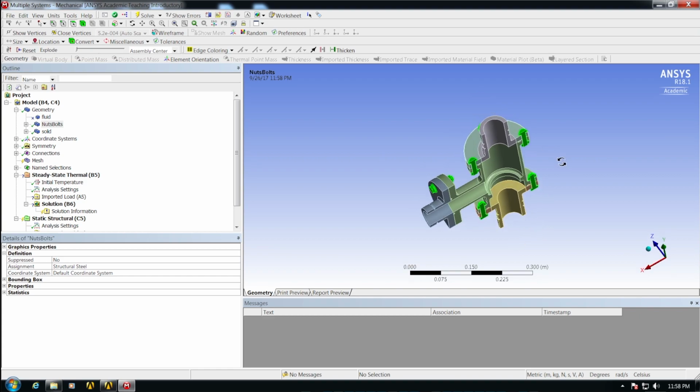One important thing to mention is you'll notice that this is cut along the XY plane down the middle. The reason is that this is a symmetric simulation. If you were to imagine fluid flowing through this pipe, the mean quantities of the fluid flow, the heat transfer, everything are symmetric about this plane. So they should be a mirror image of each other about this plane. This accomplishes two things. The first is that we don't have to generate a mesh for the entire body, which significantly cuts down on the number of nodes and elements that we use inside of our simulation. And in turn, the second thing is it really cuts down on the amount of time we need for our simulation.